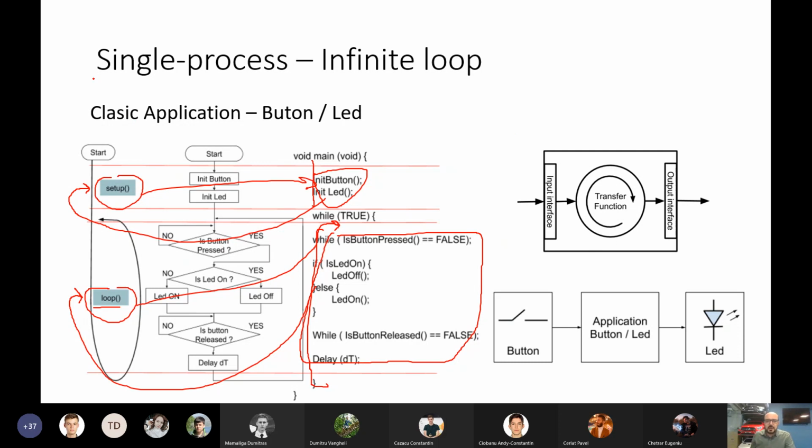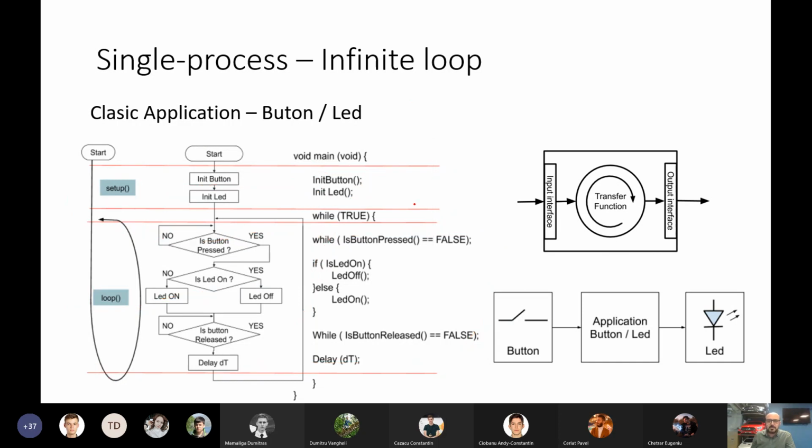Usually when we are writing some program, some application on the microcontroller, we will have a main function, where we will define something in an infinite loop. Why an infinite loop? Because let's imagine, what if this main function finishes? In this case, we'll have to exit somewhere. But where? Because we entered the application by the main function.